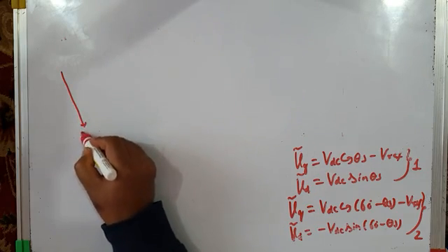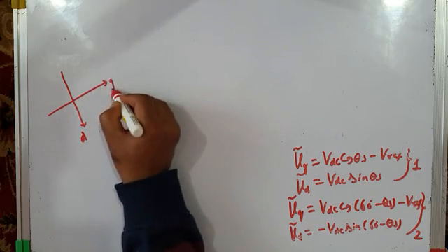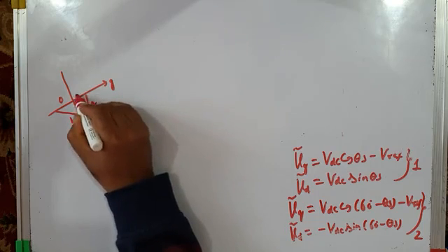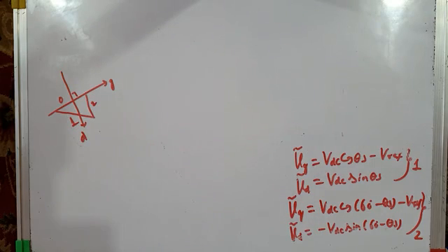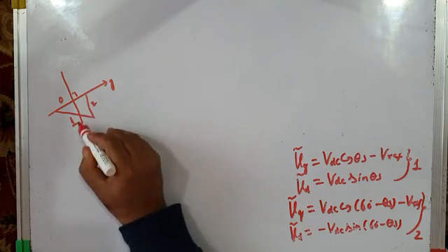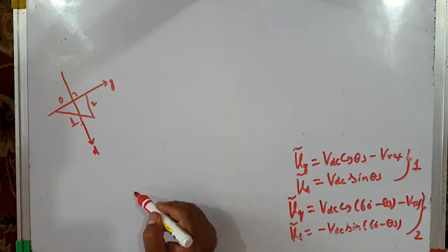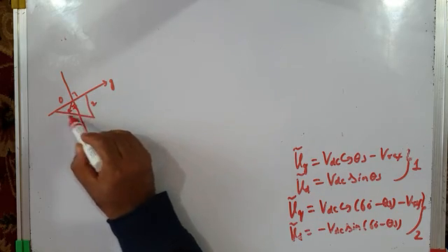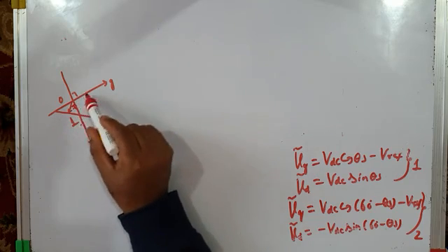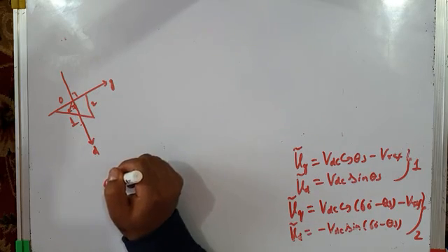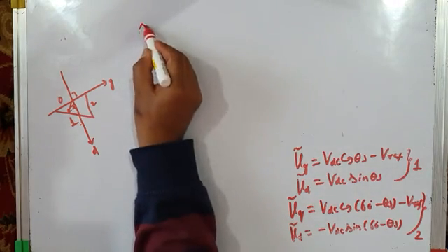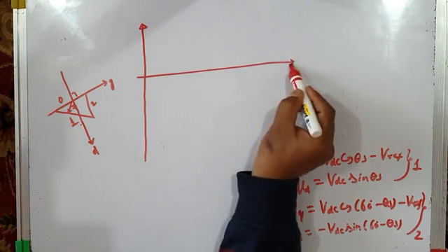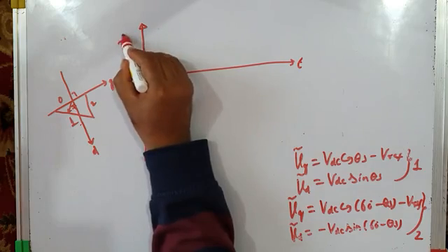So this is our D axis and this is our Q axis. So it is 0 vector, vector 1, vector 2 and vector 7. Okay, so we already know it. This is the D axis. So this is my stator flux error vector, which moves like this. Now if I resolve it into Q components and D components and draw those Q and D components as a function of time, it will be something like this. This is time axis. Let me first of all draw psi d tilde.